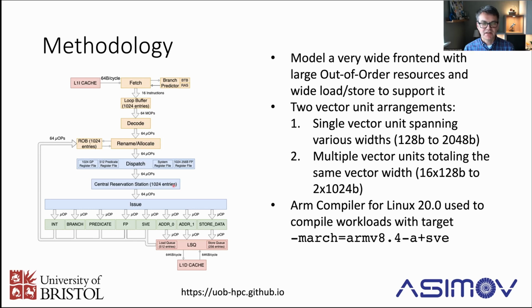He's really interested in what happens at the back end, i.e. where the execution units are. And he really wants to model what happens when I add more and more vector units, what happens if the vector units get wider and wider. And he didn't want the front end to interfere with that in any way. So for all intents and purposes, he's got an infinitely wide front end, so as many instructions being fetched and decoded and issued every cycle as you need.